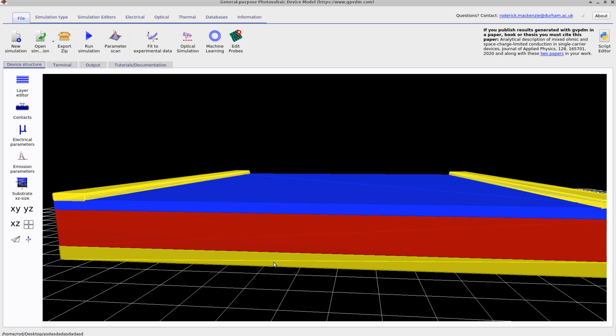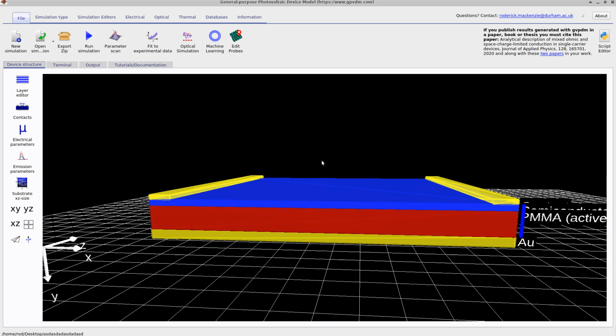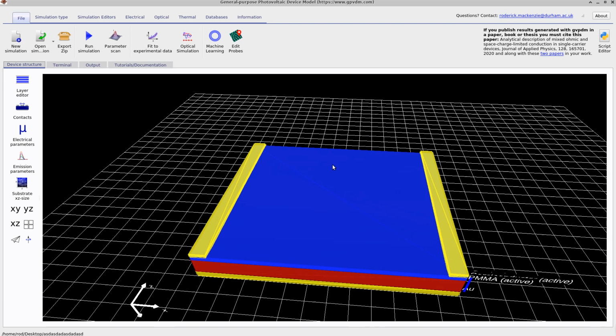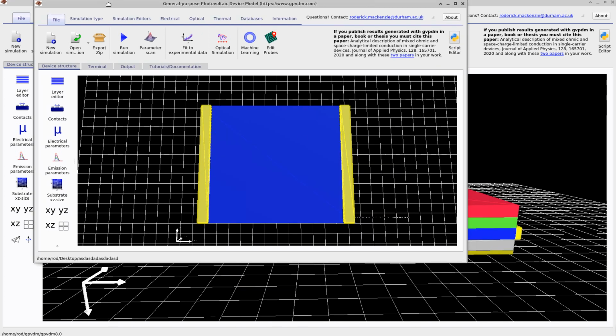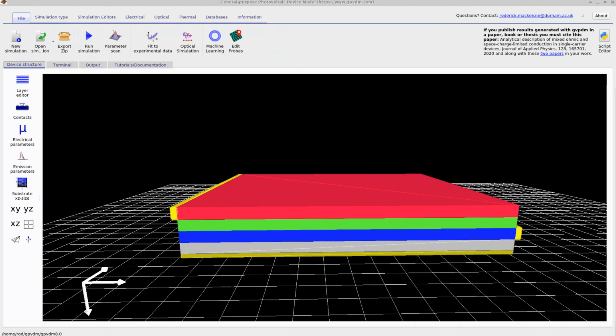And if you put a large voltage on the gate, then you generate effectively an inversion layer, which means there's lots of charge out at this semiconductor-insulator interface, and the device turns on and it conducts. That's a very interesting class of device, and it's quite a common one to make. You generally make it by evaporating these contacts onto it. Now that's all very well and good, but there's another class of device which is also very interesting that I want to talk about in this video.